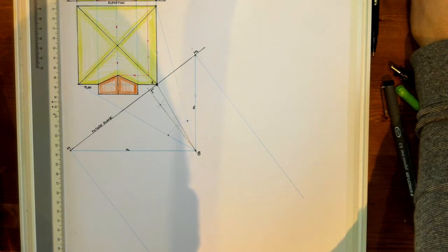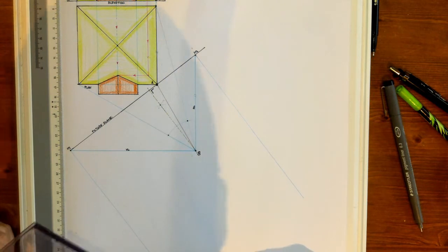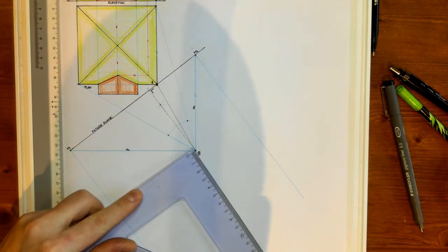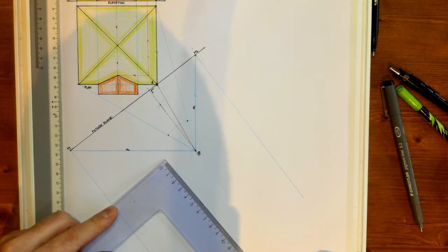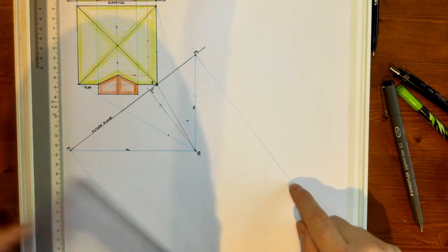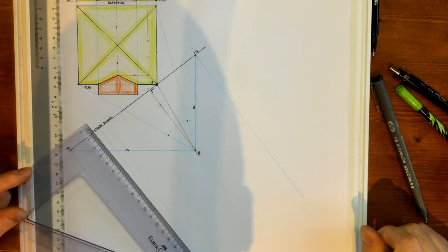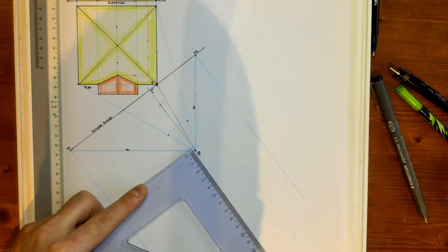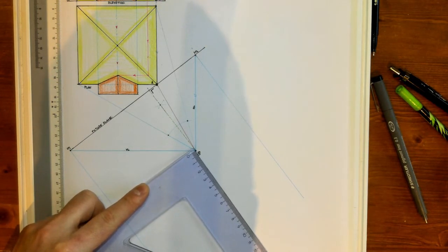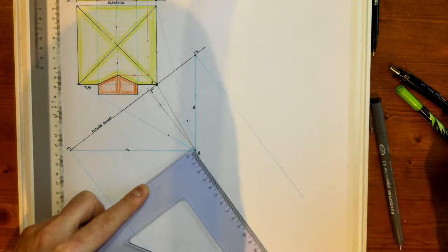Now, 5 meters at a scale of 1 is to 100 is 50 millimeters, okay? So the minimum, and I'll use S as a reference point here now, okay? The minimum I would come down here to set up my ground line is 50 millimeters. The very, very minimum. Alright? And if you have the space, position it down as far as you can, really. Okay? What I'm going to do is position it down at least 90 millimeters from S.